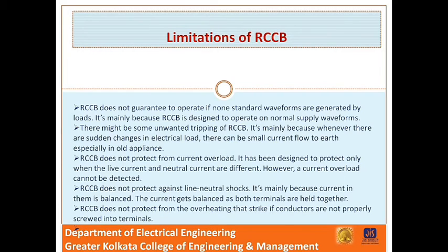What are the limitations of RCCB? RCCB does not guarantee to operate if non-standard waveforms are generated by loads. It's mainly because RCCB is designed to operate on normal supply waveform. There might be some unwanted tripping of RCCB. It is mainly because whenever there are sudden changes in electrical load, there can be small current flow to earth, especially in old appliances. RCCB does not protect from current overload.